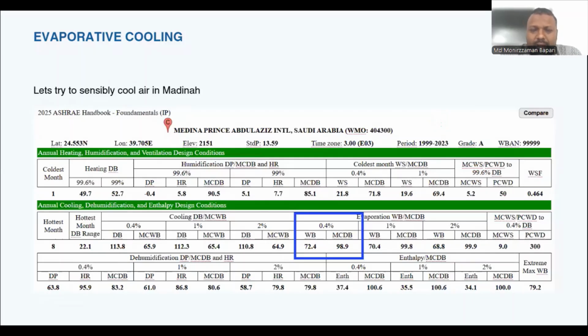Evaporative cooling, either by industrial evaporative cooler, the pad coolers, or air misting at the open spaces, and how to relate that with the psychrometric chart and stack data for the design is particularly important to learn. Very interesting. Obviously, evaporative cooling is more efficient in places with low humidity because the difference between dry bulb and wet bulb is higher, and the water at the wet bulb temperature is very low compared with the dry bulb, and that gives you a kind of comfort and better evaporative cooling.